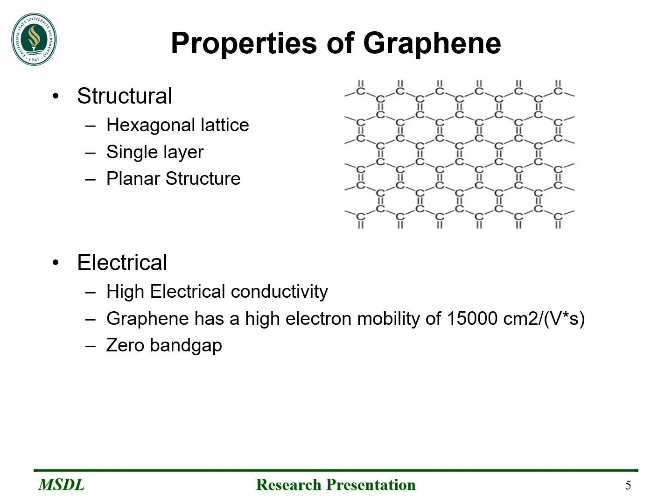It has a zero band gap, meaning that its conduction and valence bands meet at the Fermi level. This results in linear dispersion of energy near the Fermi level. This unique electronic structure gives rise to high electrical conductivity and makes it suitable for high-speed electronic devices.